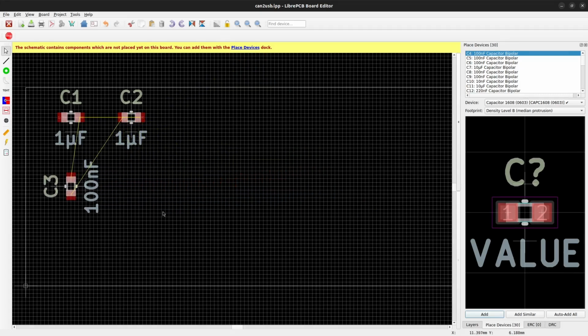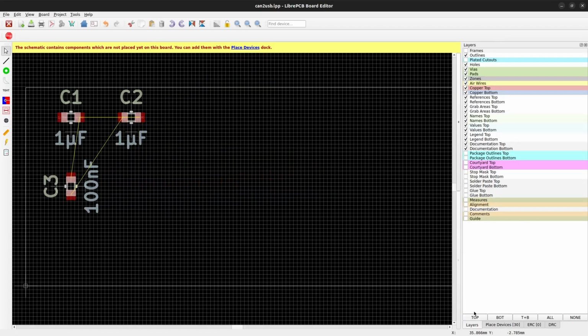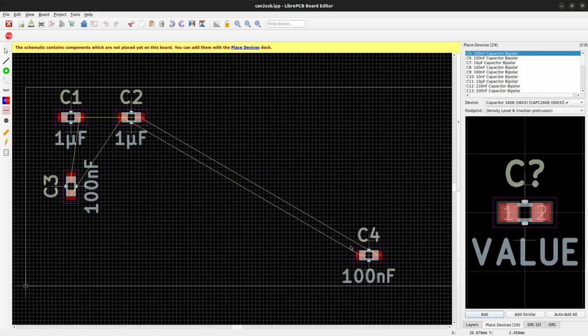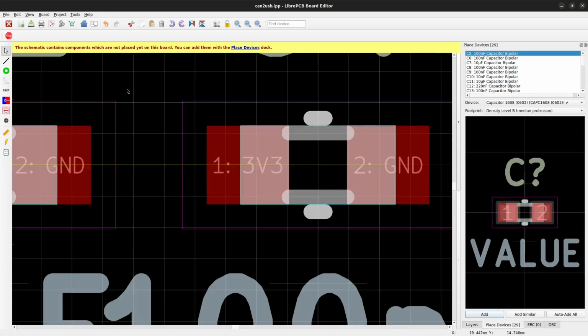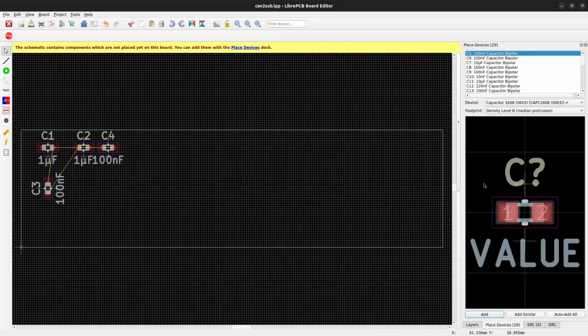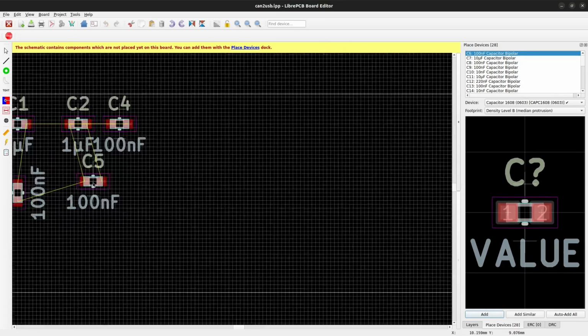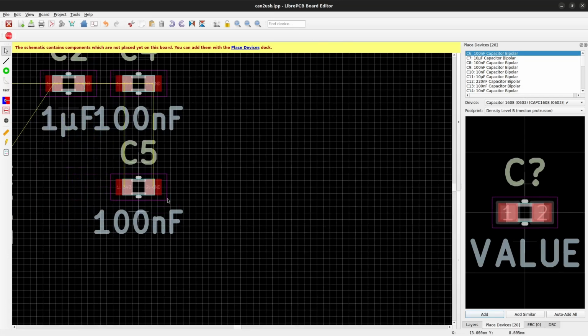To see the recommended clearance around devices, enable the package outlines and courtyard layers. Generally, the courtyard polygons should not overlap with the package outline polygons to make sure the PCB can be assembled without problems. Unfortunately, we can't give you any recommendation where to place the devices since this is individual for every project and is a matter of experience.